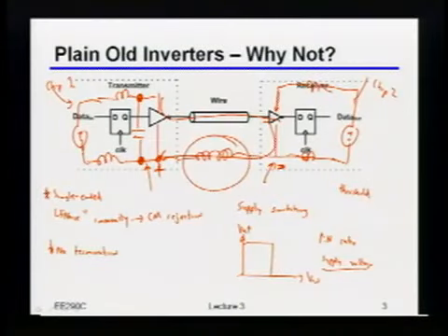Yeah? So why can't you just run the ground plane also? I mean, you do indeed run the ground plane, but the question is just how good of a job can you do really getting your signal to be strongly coupled to your local ground, both on your chip and on the chip that you're talking to, right? What I'm saying is instead of running the wire like that, you run the ground also. By the way, I think what you're saying is why don't you just run a differential signal? Yeah, exactly. Right, which indeed is a lot of times what you're going to try and do.